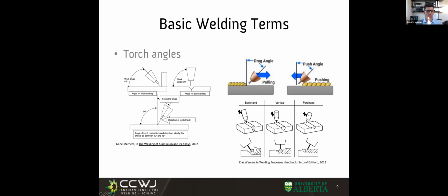Now, imagine you're welding, making a fillet weld, and you'll know soon what fillet welds are, right? And then you have the work angle. Of course, in a fillet weld at 90 degrees, sometimes you want to have 45 degrees. This makes sense, but it's not always. And if you look at the Lincoln Procedure Handbook for fillet welds, you'll see that sometimes it says you should have different angles other than 45. Sometimes you should aim the torch a little bit more towards the top part or the bottom part. They mention all those things.